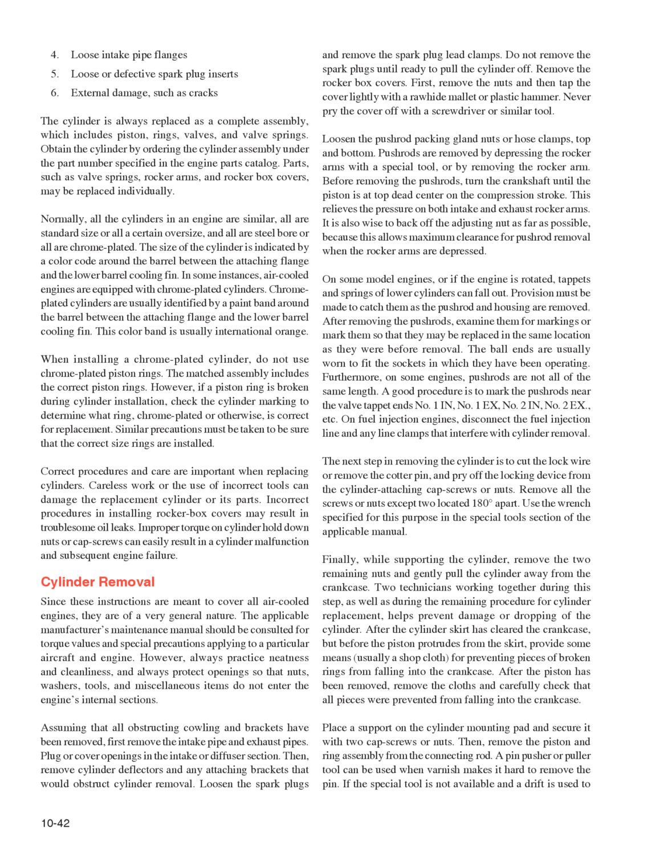Cylinder removal. Since these instructions are meant to cover all air-cooled engines, they are of a very general nature. The applicable manufacturer's maintenance manual should be consulted for torque values and special precautions applying to a particular aircraft and engine. However, always practice neatness and cleanliness, and always protect openings so that nuts, washers, tools, and miscellaneous items do not enter the engine's internal sections.